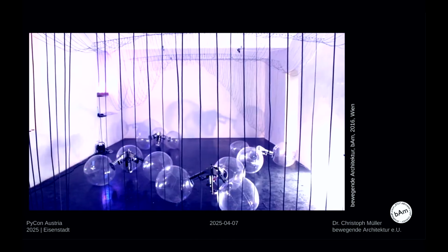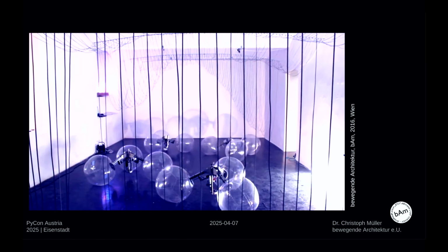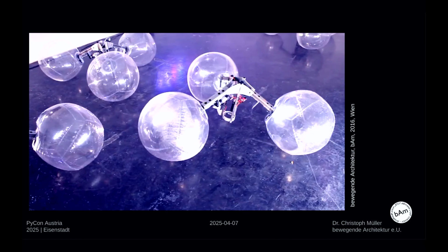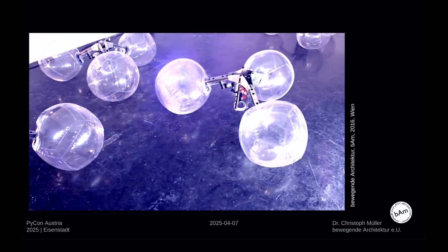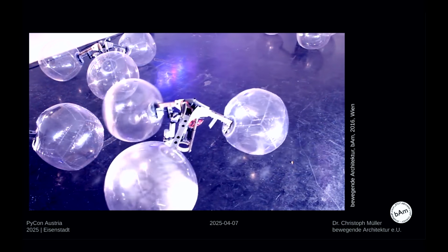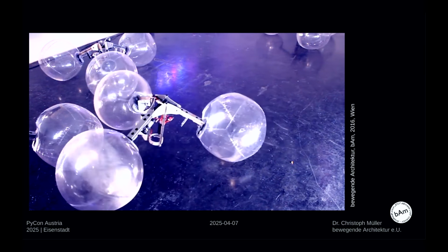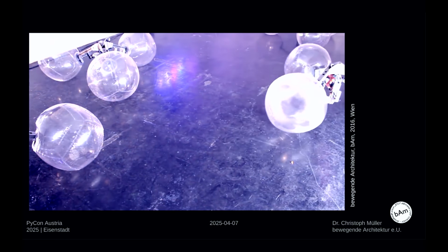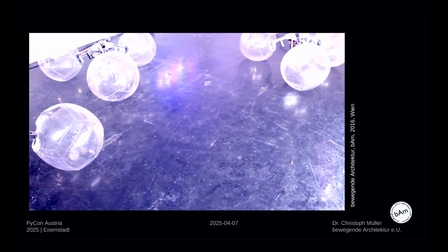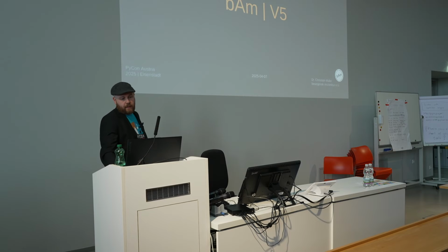Basically, Raspberry Pi is dealing with all the internet connection, is somehow the brain of this robot. And the Arduino is handling the hardware. So there are simple Hall sensors that are measuring the actual position. Again, here the recognition of the other modules is based on OpenCV. It is a circle detection that is trying to catch the other's sphere, and from the radius of the detected circles, distance, etc., can be calculated.